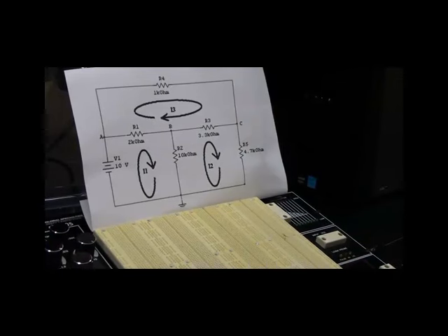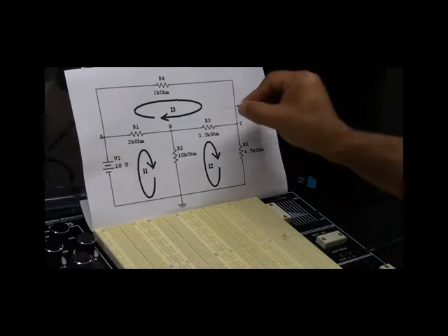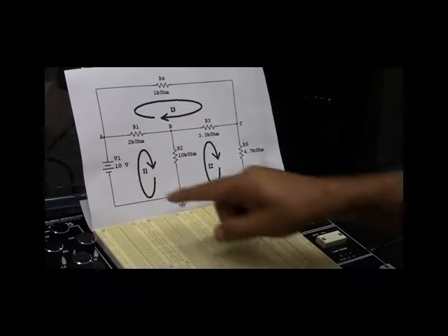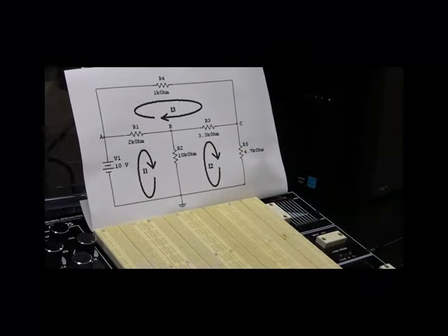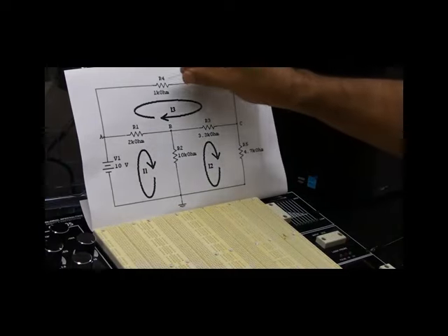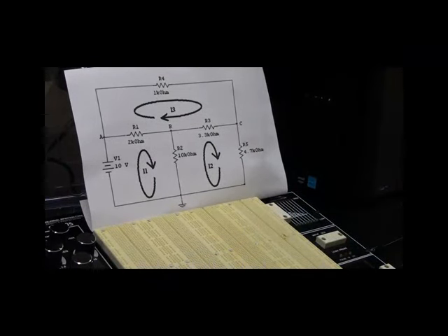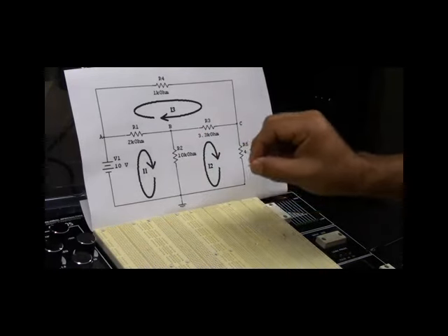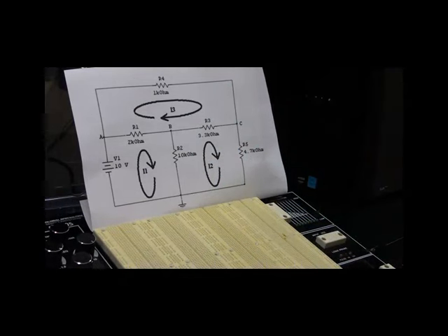So let's start with implementing a circuit. In this circuit on the paper, we have 3 loops that are connected together, and it's supplied by a 10-volt power supply. The professional way of doing it is to follow the topology of the circuit. If you see a resistor which is horizontal, same as R1, R3, and R4, then you implement it in a horizontal way. If you see a resistor which is vertical, try to implement it on the breadboard in a vertical way.